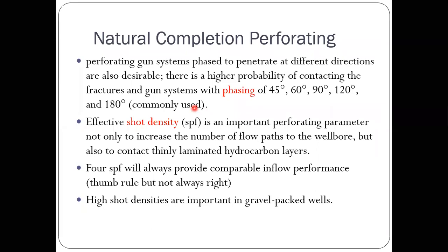According to case studies and laboratory studies, only 50 to 70 percent of the perforations are actually effective. So you also have to consider this. You have to create a few more perforations, because you have to assume that only around 50 to 70 percent will contribute to the production.